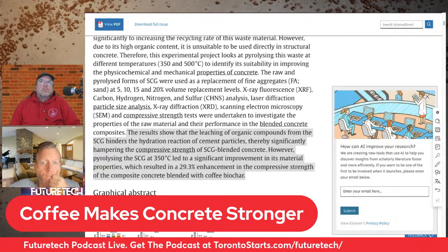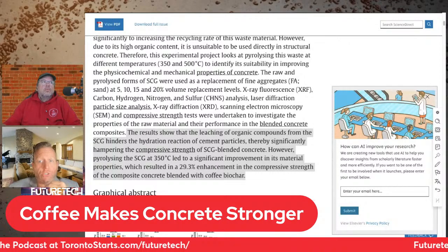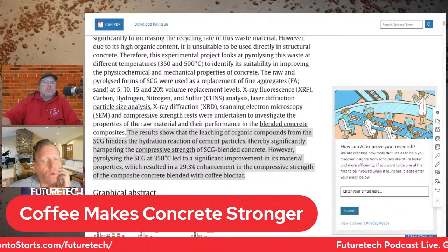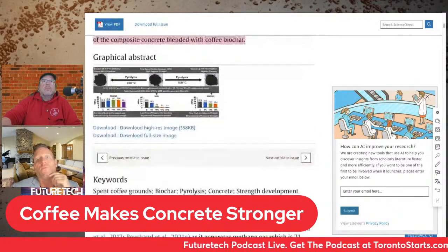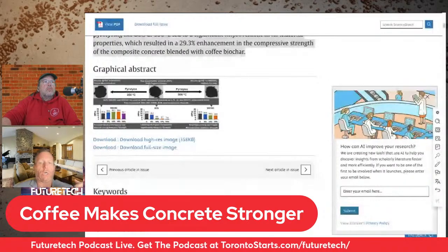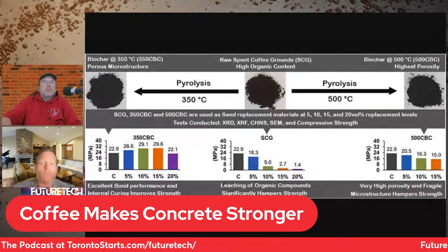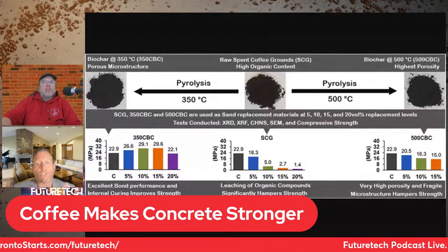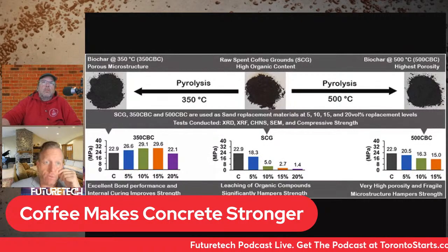So beyond the optimal percentage, the excess coffee ground biochar just takes space and weakens the overall concrete binding. There's a limit, because there's only so much cement particles that can mix with the biochar. And so if you add too much of the coffee ground biochar, then you have excess that's just going to sit there, kind of thing. And that could potentially degrade, like you were talking about.